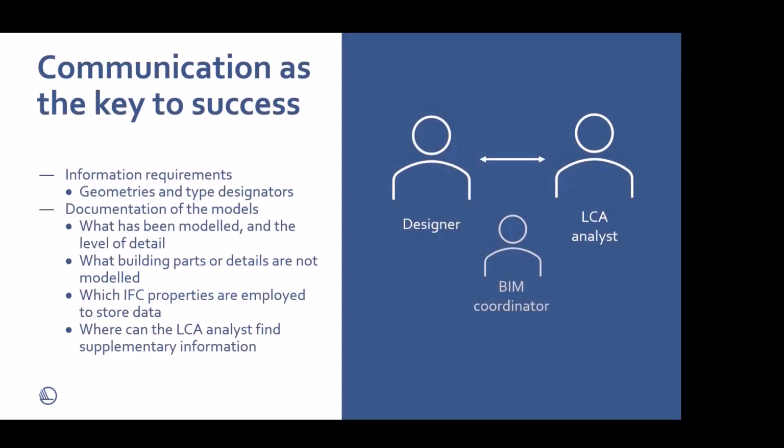In any project where there are multiple design models or several people participating in the process, the best way to ensure efficient calculation process and correct LCA results is to communicate the LCA-related information requirements from the beginning of the project. Additionally, any model aimed for LCA purposes should be accompanied with the documentation of what has been modeled, what is the level of detail, which building parts or details are excluded, and which properties are used to store the data.